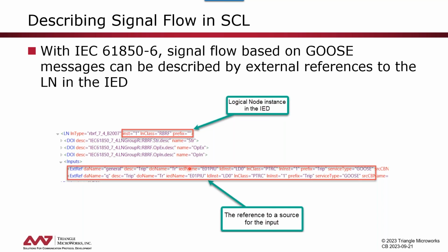It's the breaker failure initiate input that we have seen before. So that can be documented through an XREF. We can also indicate what service we will use, and we could also indicate where the control block is associated to that GOOSE message.